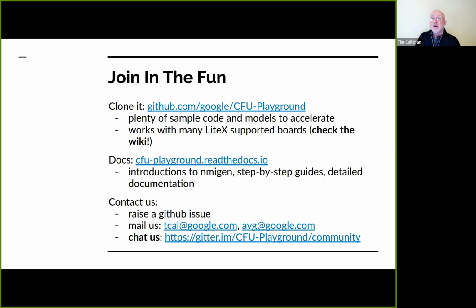With Fomu, we usually run at 12 megahertz, but that is not so much that it can't run faster. It's kind of tied to the USB 48 megahertz frequency. For example, with Icebreaker, I think we run at 24 megahertz, so double that. And certainly running faster than 100 megahertz is possible.